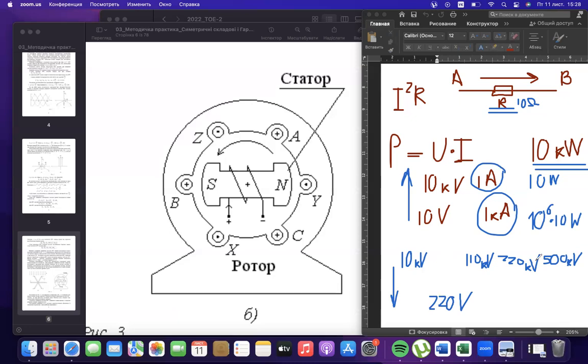And for this purpose, a quite useful thing is transformers. Transformers operate on a magnetic field. It is generally 2 coils with a ferromagnetic core inside. The ferromagnetic core is just for concentrating the magnetic field, but generally it's just 2 single coils.